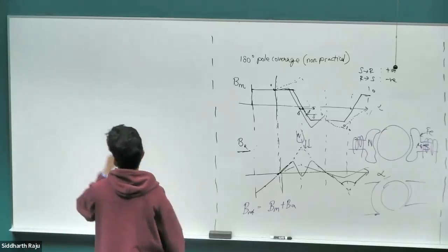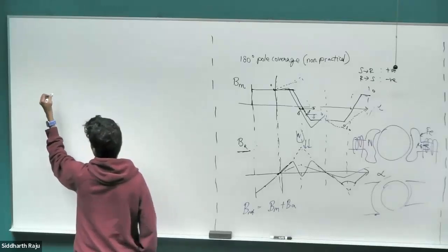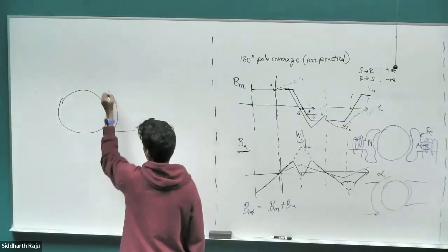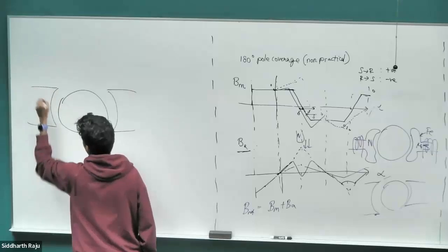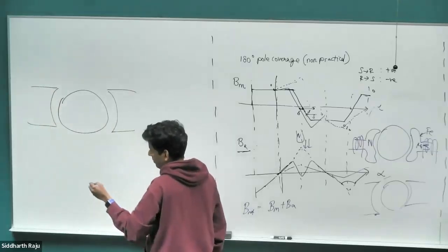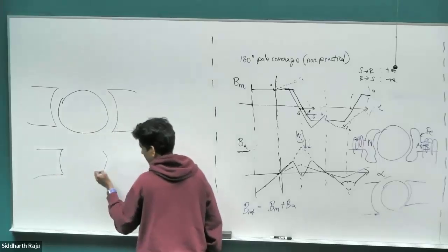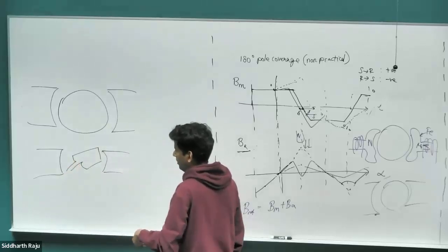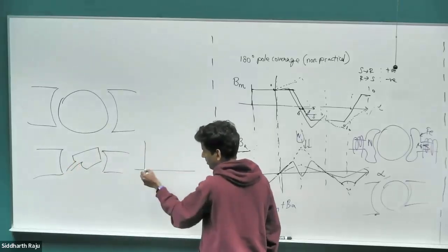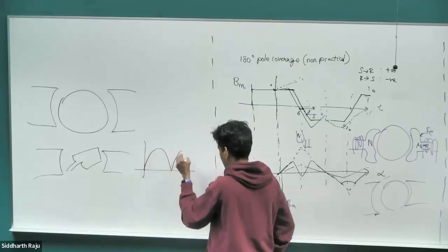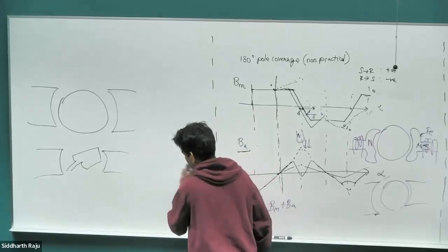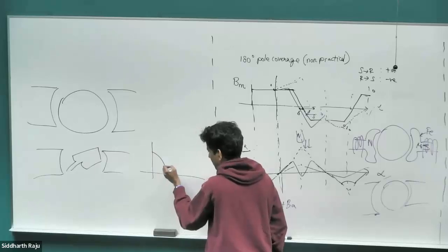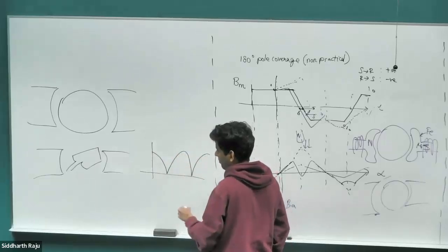Okay, we have 5 minutes. Okay, so last week we derived the expression for the torque and the expression for the EMF of a DC motor. So we started off with the hypothetical case where we just had this coil in the air gap without an iron core, and we figured out what the torque due to that one coil is going to look like. And at angle alpha equal to 0, when it's planar to the magnetic field, torque would have been maximum. And when it's at 90 degrees, all the force would have been perpendicular, there would have been no torque.